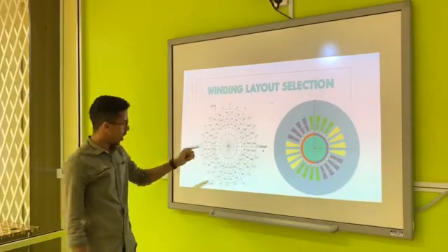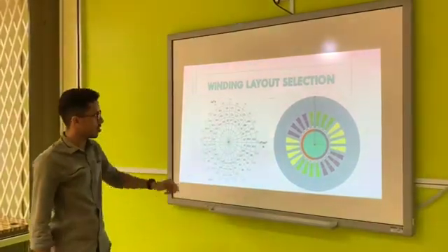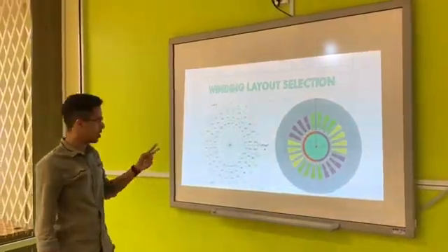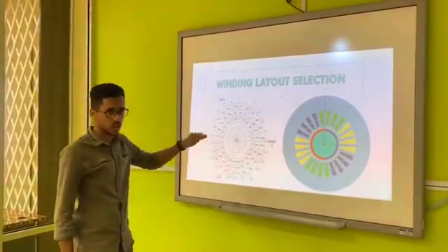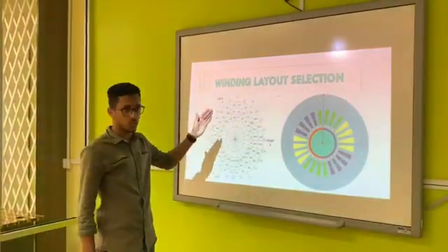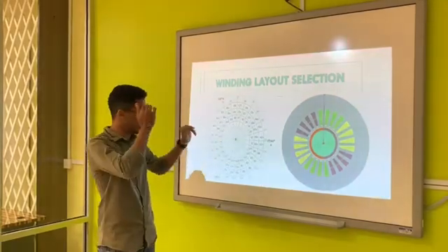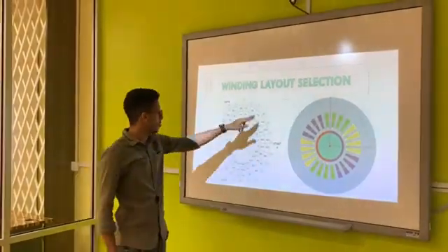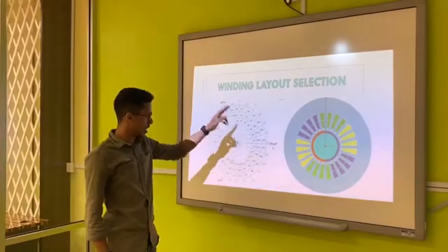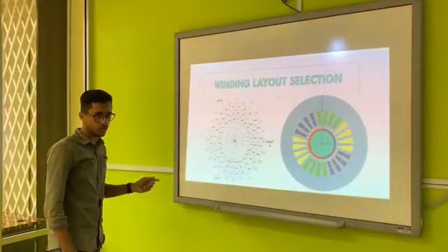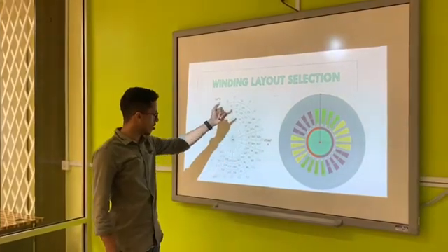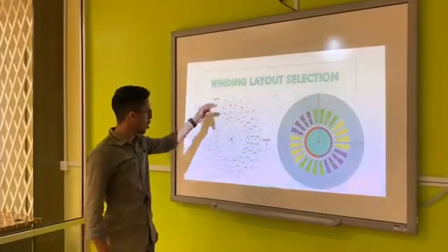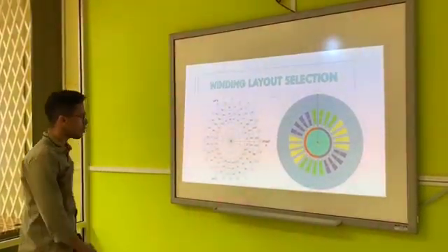Then we have the vectors, so after we calculate the angle, it's 15 degrees from slot to slot. Basically it's 24 vectors based on the slots. And we also have the slot distribution from S1 to S24.